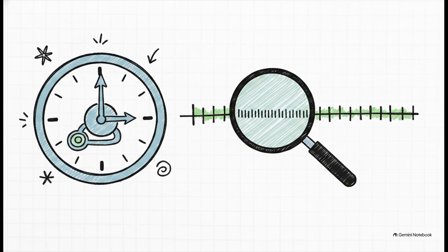Line 1 is a compiler directive setting the timescale. The first part, 1 nanosecond, sets the base unit of simulation time. The second part, 1 picosecond, sets the resolution. This is incredibly important because it specifies the exact granularity of time for which the simulator will evaluate signal values. It's essentially setting up the master clock of our entire virtual universe.